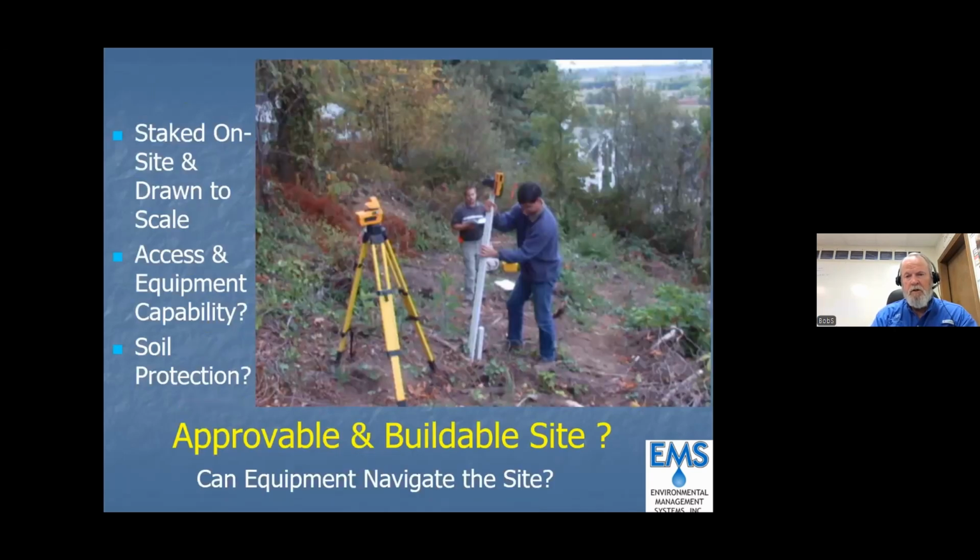And not only do you have to look at the site and the soil, but can you actually get your equipment there? Can you navigate to the site? If it's too steep, can you actually build it? And of course, when you're on a steep slope, then that water moving down slope can cause erosion. So you need to be able to slow that down with check dams or infiltration trenches. Natural vegetation is another thing that you want to keep in place as much as possible.